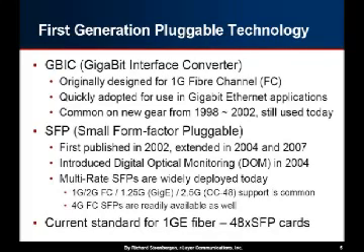and it actually does a couple things. It's multi-rate, so you can use the same pluggable for 1 gig, 2 gig Fibre Channel. You can use the same pluggable in Ethernet, and now these days it's almost impossible to find one that you can't also take, put in an OC48, and run it that way. And these days, for a few dollars more, you can get the ones that also do 4 gig Fibre Channel. And if Ethernet cared, they could do 4 gig Ethernet over the same type of thing. But these are very flexible optics.